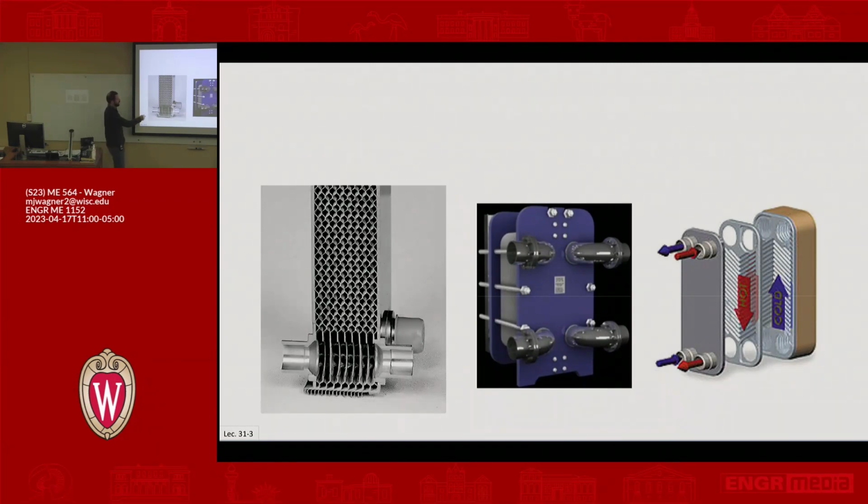So now you look at these heat exchangers and you see what's happening. So you have flow. Let's say this is a header down here, I guess. Flow's coming in this way, it's probably leaving in the back through another port. And then there's tubes that go up and down, and then there's all these fins that connect it. So this particular device probably has maybe air or some gas that's flowing this way through it. And then in crossflow, whatever's contained in here, maybe it's a refrigerant or whatever. So that's taking advantage of these fins, essentially, to increase the heat transfer area, and it's a more effective heat exchanger. All right, so this is probably a crossflow, fin-type heat exchanger.